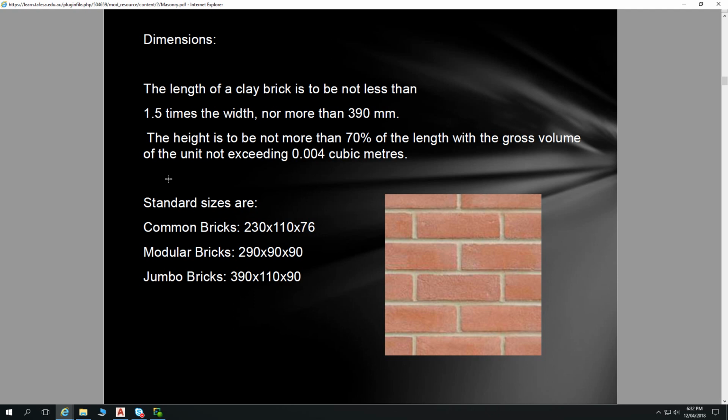The other reason is that you can change the modular brick to be more in keeping with other dimensions within the building, but our window sizes are already predetermined. And it's another thing to go convincing window manufacturers to change all their window sizes to increments of 300mm rather than increments of a 230 brick.